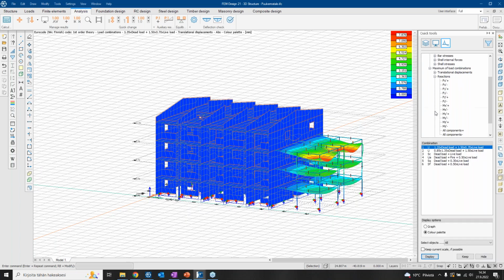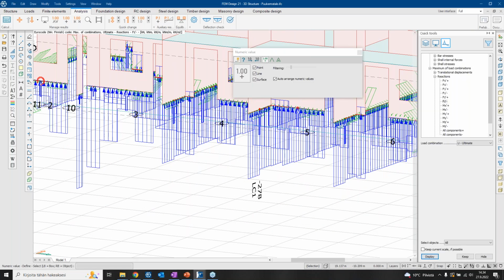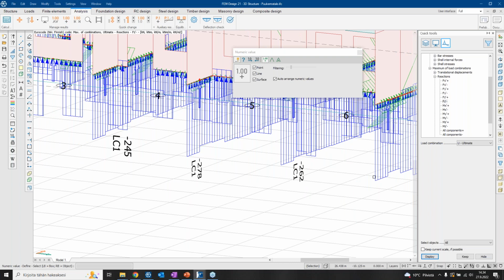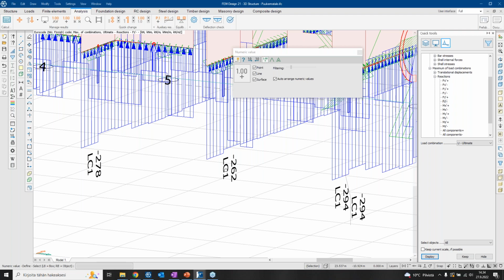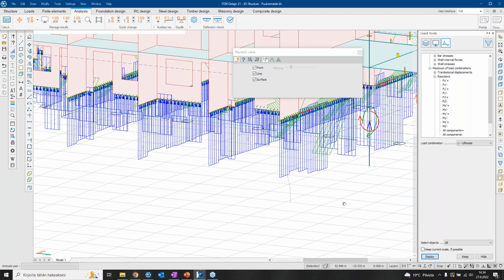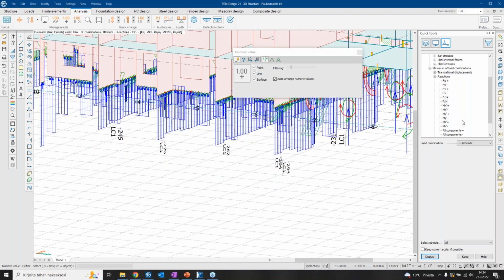What I wanted to show you is this maximum of load combinations, and I want to check which combination creates the maximum compression. And I can check the results here. Just a few, and it says the load case number 1. So if there would be any other load case that gives the bigger value, it says load combination X or Y or 2 or 3. Yeah, I guess this is for the IFC file. We can return to this also.